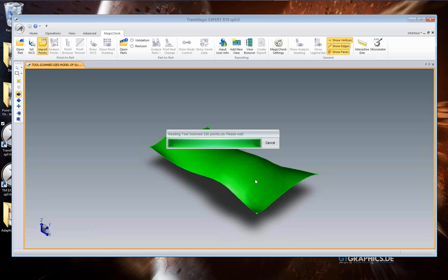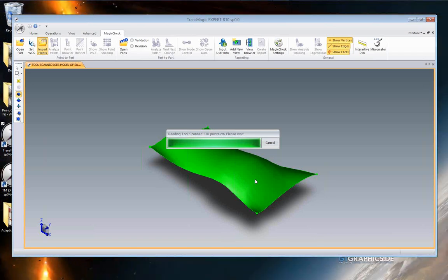We will have, in the future, the ability to detect surface normals when you're not working on a solid model. Because with a solid model, you know inside and outside. You have a contained volume. But with a surface model, we detect anything outside of that surface as simply an outside measurement, even if it's on the bottom side of the surface. So in the future, we'll take into account the surface normal, and if it's the reverse of the surface normal, we'll consider that an inside. But currently, what you're going to get is outside measurements.